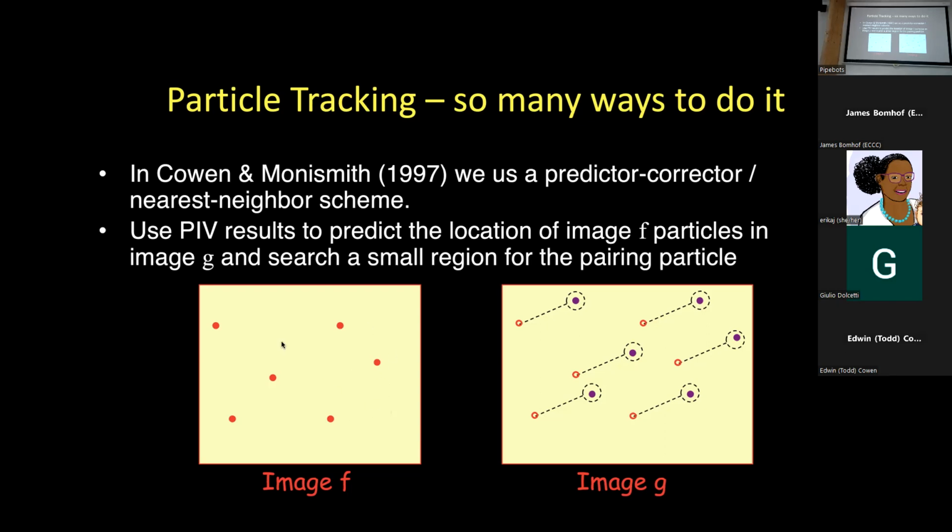I'll talk a bit more in a minute about how we solve some of those problems, but one simple solution is, if you can get a crude estimate, and by crude, I mean a pretty good estimate still, based on PIV of what the average displacement is, well, now I can use a predictor-corrector algorithm and predict the displacement of every particle in the subwindow based on that mean PIV-based estimate, and then draw a very small search radius around that location and ask myself the question, is a particle in that search radius? And if I've got a pretty good estimate and the turbulence is strong, but not insanely strong, then that search radius is small compared to the mean displacement. And I can confine my search radius to a region that ends up being only about 2 pixels and very effectively find all of these particles.